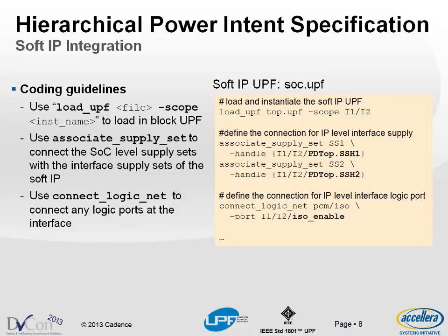Once you have this IP power intent, then how you hook up, right? That's the key thing. UPF 2.0 gives you a very systematic approach to link, combine, instantiate or integrate your soft IP into SoC designs. Several key things to remember. Load UPF-scope. This is the command to load your IP level UPF to SoC level. Eric talked about that. Then, again, associate supply set to link the interface supply with the top level SoC level supplies,